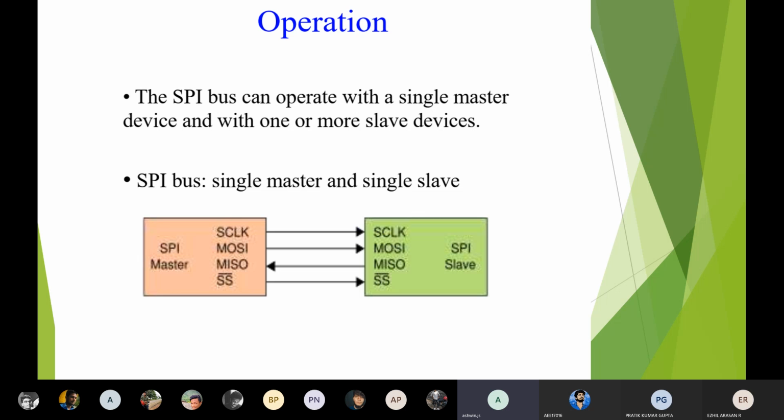First, it will make the clock pulse given to the slave. It may be a falling edge, I mean negative edge triggering. Once it is given, the slave becomes active to transfer or receive the data. Here the chip select is not required when there is only one slave. If you are connecting multiple slaves, the slave select pin will be required.